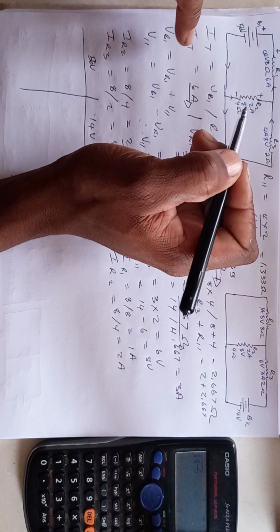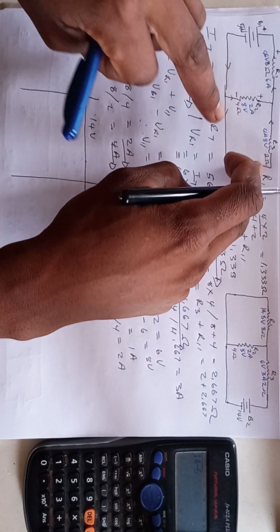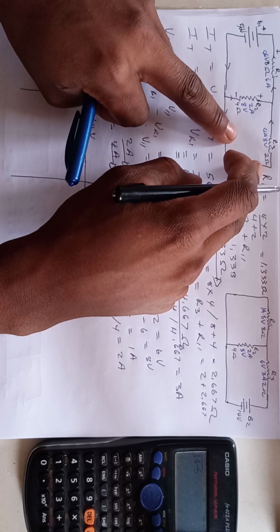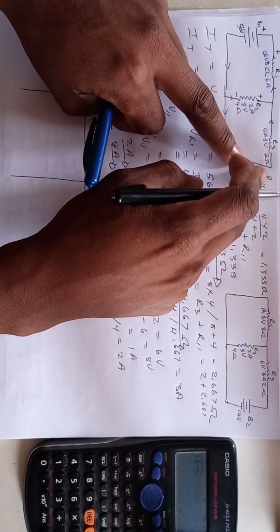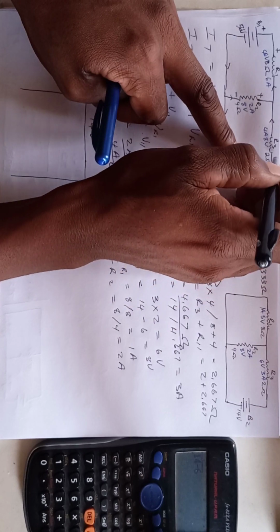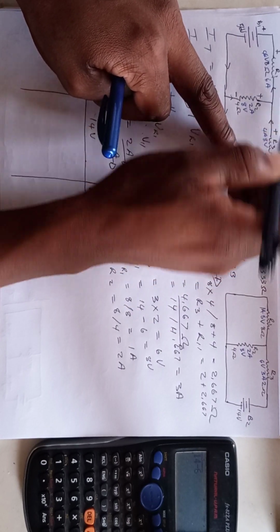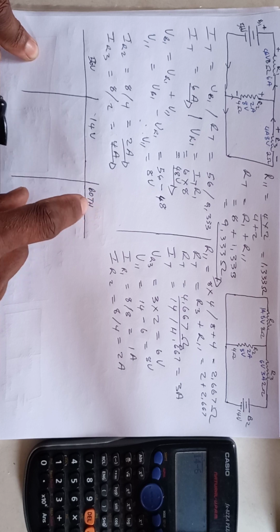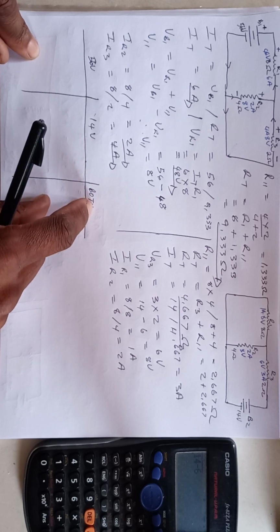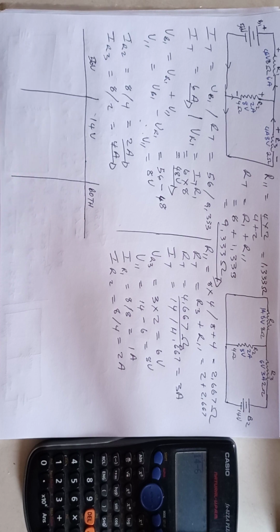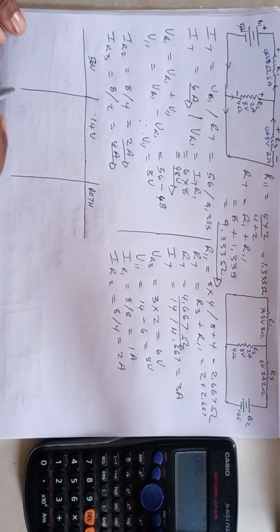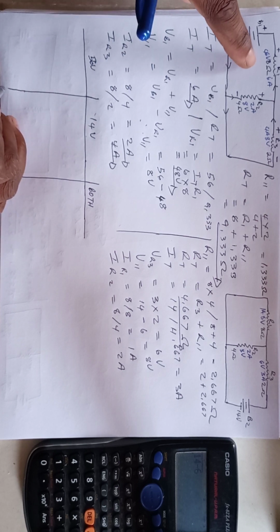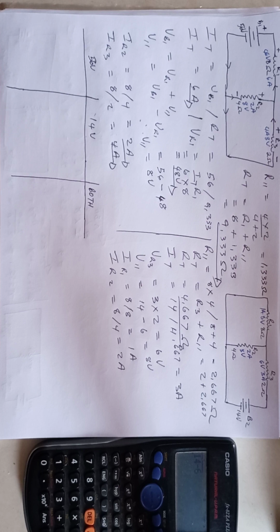Again, the other thing that is important to note here on R3 is that if electrons took this direction and enter there, this becomes negative and this becomes positive. The polarity is very important because it's what we're going to use to determine the voltages for this circuit. So now let us write everything that we know on that circuit only in voltages.